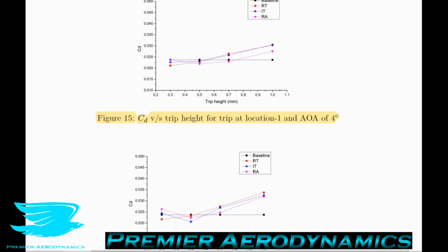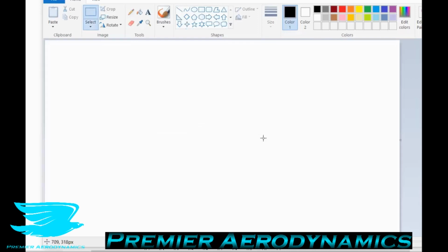So the purpose of providing a boundary layer trip is to control the formation of the laminar separation bubble and hence reduce the bubble drag. The bubble drag here is just the additional drag that the LSB is forming. Now this is quite interesting because there are quite a few different angles that we can look at in terms of what drag the LSB is producing and or reducing.